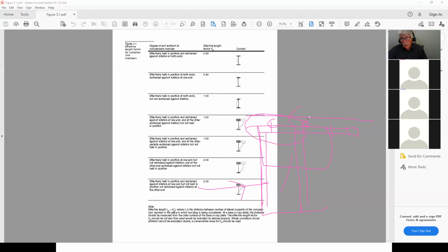You follow? But if you don't have this transfer mechanism, in other words, from the wind that blows here or the load, if you don't have a transfer mechanism that can bring it to here and then the wall can actually resist that, everything's going to collapse on you. So that's what you have to be careful about. As long as I have an element that can take the lateral forces and transfer those to the foundation, not a problem. You see? And a lot of people forget to do this. Some people put a header there and then they put planks, and the planks might not be able to transfer. And then all of a sudden the thing gets distorted.